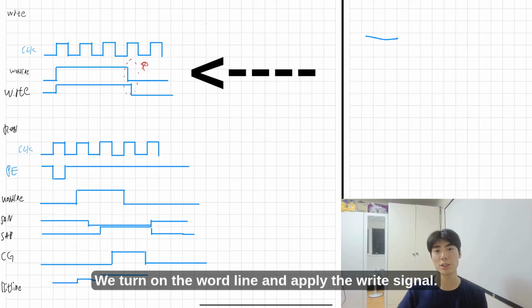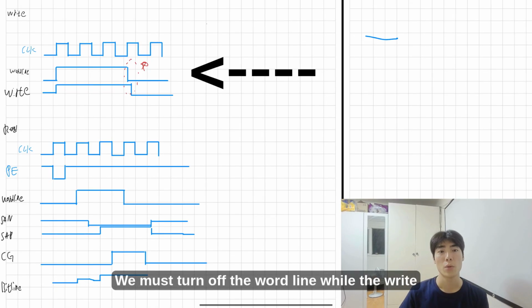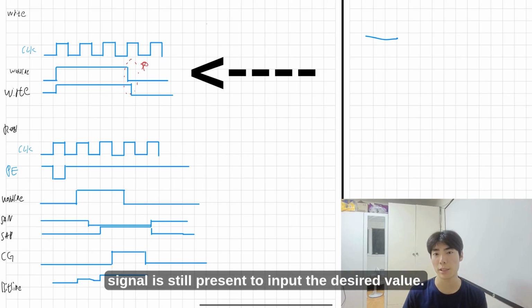This is the write operation. We turn on the word line and apply the write signal. We must turn off the word line while the write signal is still present to input the desired value.